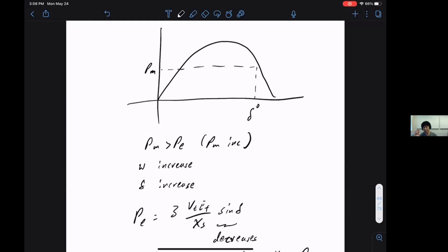When you're operating the system, say through a transmission line or between a generator and the grid, your constraint is that the angle needs to be much, much smaller than 90. Normally it's a 45 degrees angle constraint. Your max angle can only be 45 degrees apart. Under that constraint, even if your angle is slightly larger, it is still very far from 90. So that's building a safety margin.